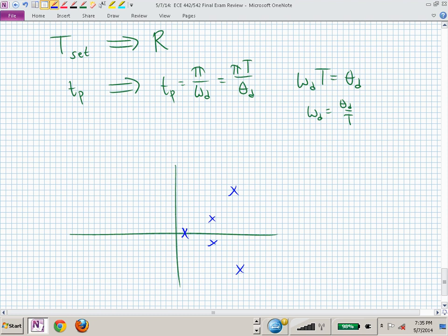We pick the dominant poles, don't we? I hope he gives me full credit for that. Define dominant, right? That's what I would ask. I would say, you didn't tell me what dominant means. What's dominant mean? The ones that are moving the slowest, right? I'm assuming now these are all inside the unit circle. So we're stable, so they can actually dominate.